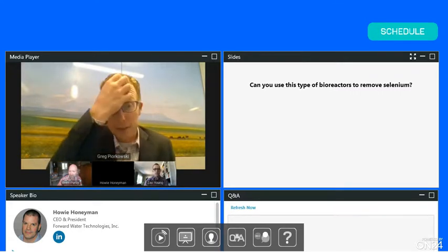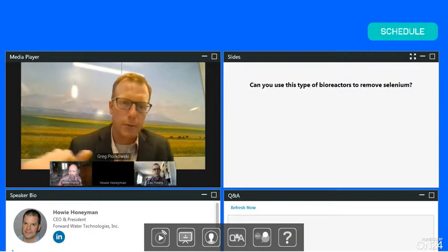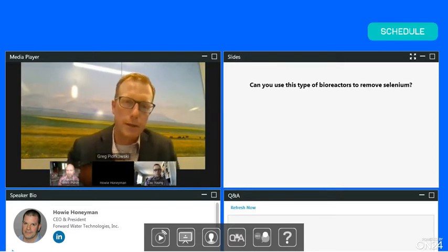whereas nitrate is basically just so what happens is the bacteria degrade organic material and then they're looking for an electron acceptor. So oxygen is the primary one. Just under oxygen is nitrate. So it actually doesn't take much of a depression in the electric potential for it to get knocked down and for that to get reduced to nitrogen gas. So things like selenium and sulfate are further down and just require a much more anoxic and reducing environment.